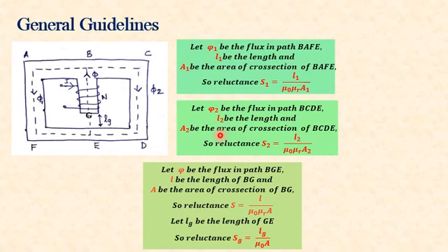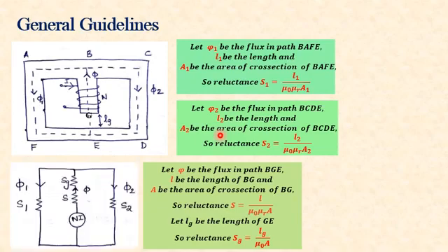Now, the electrical equivalent of the above circuit can be drawn like this. Here we can see that the source is placed in the central limb. The source is Ni. Then in the central limb, the flux is phi, but this flux is traveling through two materials. One is having a reluctance S and the other one is having a reluctance Sg. And these two are connected in series.